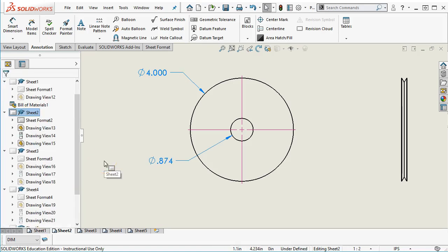Okay, so we applied the 874, and that is a press fit, but my intention is not shown. The drawing does not show the intention that a bearing presses in there, only by putting the tolerances on, because at this point it's still plus or minus 5. My high side on the analysis would be 879, and my low side would be 869. So I can't have that and have the bearing do what it's intended to do.